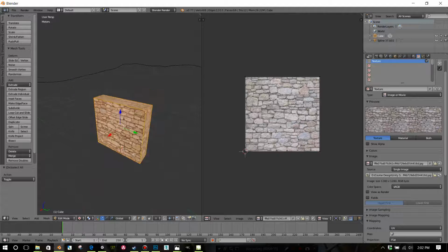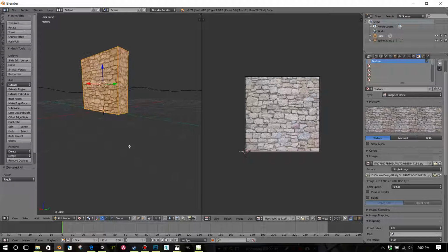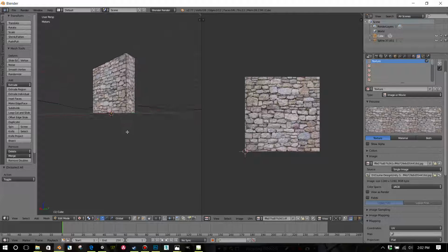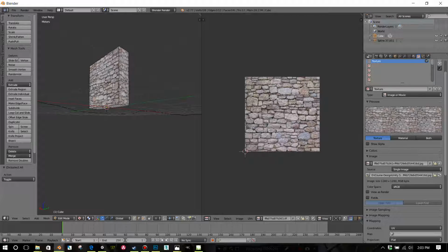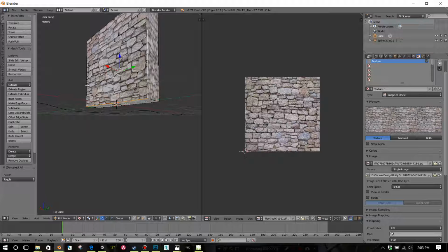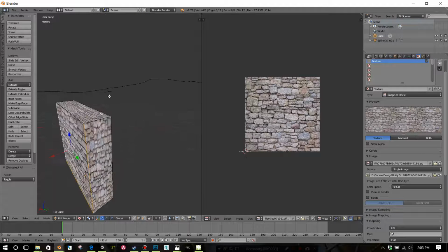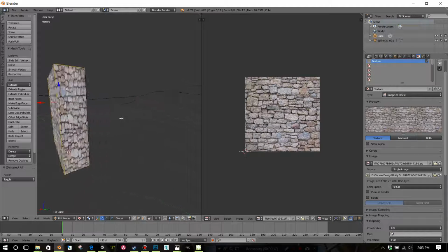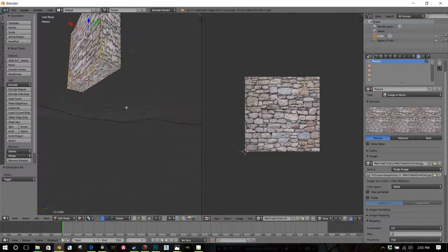So we want it to be a more uniform unwrap. If it's a box, you're going to have to mark some seams here. The way you do that is you think of this like scissors, and this is always a little tough to get accustomed to, and I screw up sometimes. But if you go to edge select and pick edges, and you're just doing Shift left mouse, think of it like scissors cutting this around, and then you're going to lay this whole object flat.